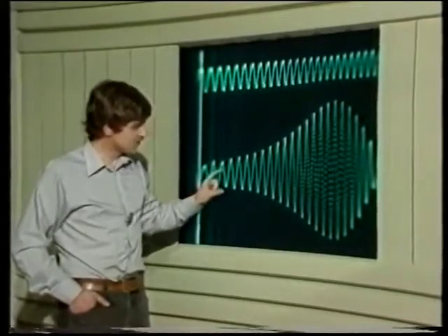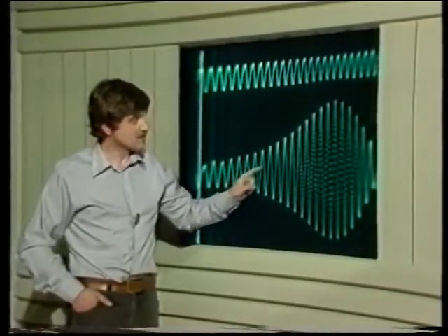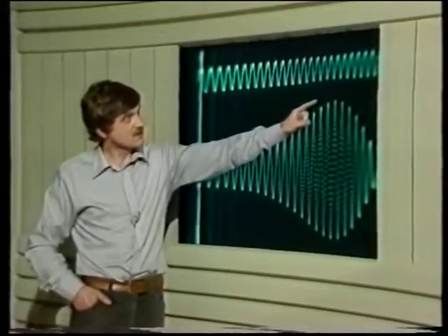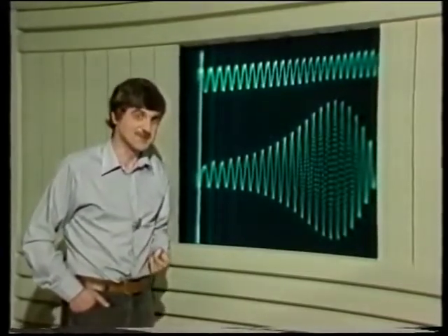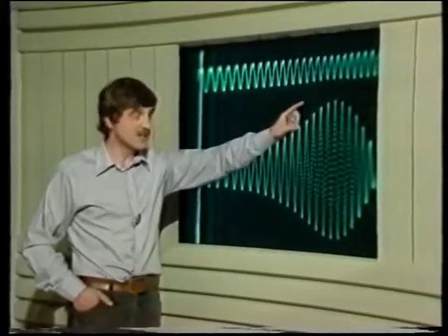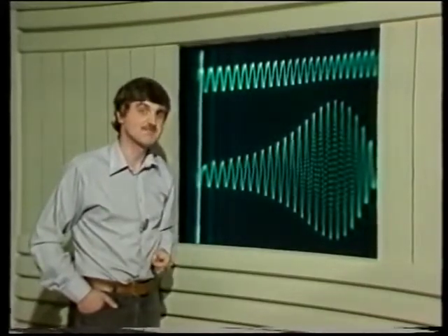And here the output amplitude increases rapidly with frequency up to a peak and then dies away again. This peak is associated with those rather extreme oscillations you saw and are characteristic of a phenomenon called resonance. It's a condition which designers try very hard to avoid. In fact, this peak occurs at a particular frequency for a given vibrating system, and that frequency is called the resonant frequency of the system.